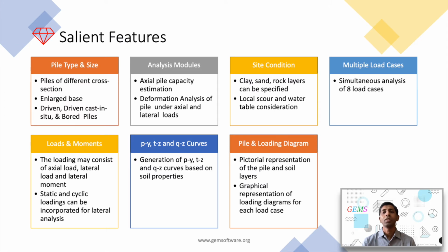Some of the salient features are: the application can analyze driven, cast in situ, and bored piles. Piles of different cross-section and with enlarged base can be evaluated. It offers axial pile capacity estimation, load settlement analysis, and lateral pile analysis of piles under combined lateral and axial loads. Various soil types, clay, sand, and rock, and soil conditions such as groundwater table and scour can be taken into account in the analysis. Simultaneous analysis of up to 8 loading scenarios is possible.